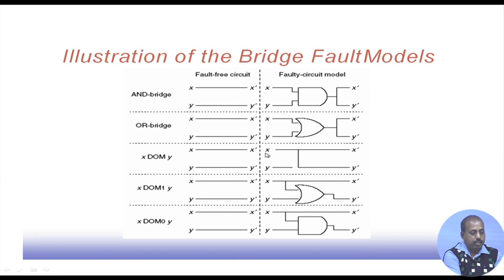So, we just see that under the constraint that this y value is 0, are we getting the value of x at the y dash, or similarly with value of y being equal to 1, are we getting the value of x at the y dash. So, the ATPG tool can be modified to put this type of constraints, and we can see the test pattern generated by them for this purpose.